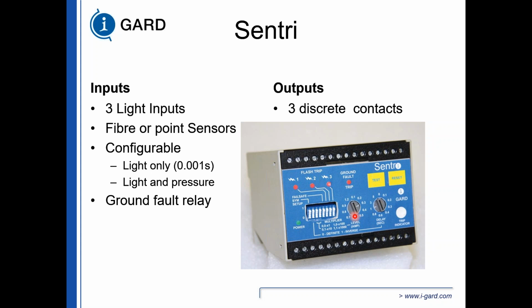If you combine it with our HMI, you have an infinite number of ground fault pickups that you can choose from. Right now, it's a direct replacement for the MGFR, provided you choose the right multiplier. But this relay allows you to basically segregate where the fault is. So, for example, say you don't have a ground fault, but you have a 3-high section of circuit breakers. If you have a light sensor going to the back of the cable compartment of the top breaker, you can trip only the top breaker if you witness a ground or arc flash in that compartment.